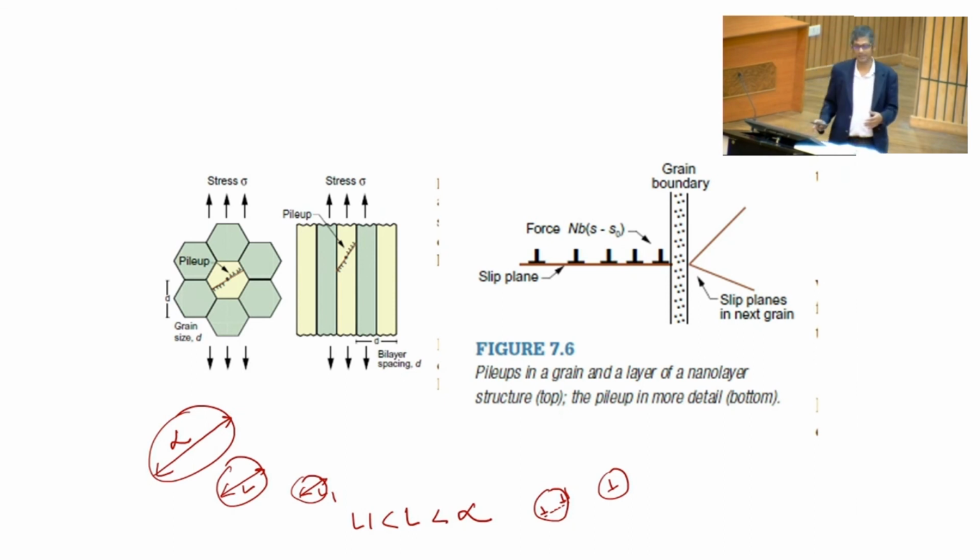So now you understand, right? That is what is happening as you decrease the grain size. As you keep on decreasing the grain size, the number of dislocations inside the grain is decreasing till it reaches 1 or 2 in the grain. Once it reaches that value of the grain size, when only 1 or 2 dislocations can be accommodated inside the grain, the Hall-Petch equation loses its meaning, because then the concept of pile up and the stress acting on the grain boundary is no longer happening.